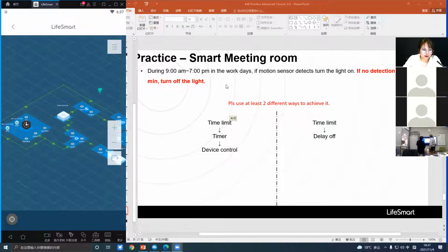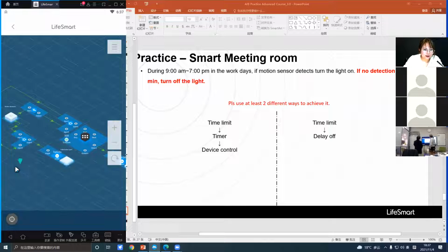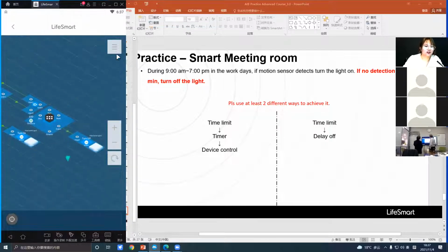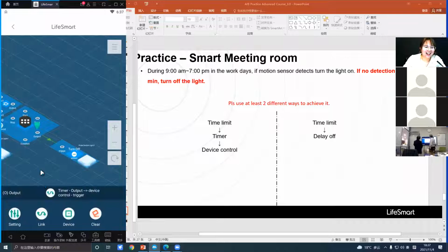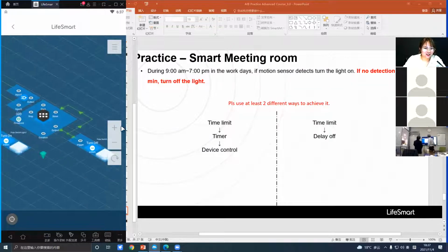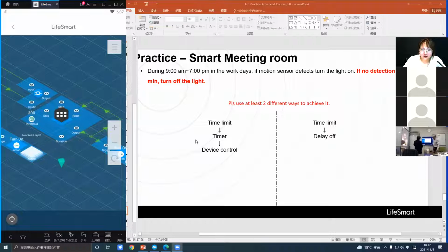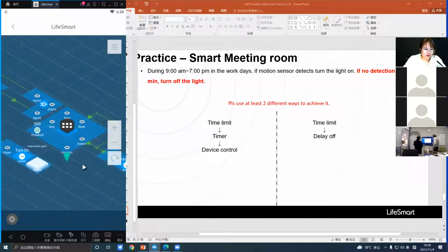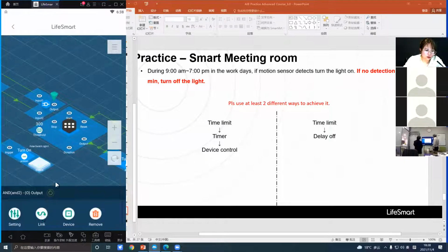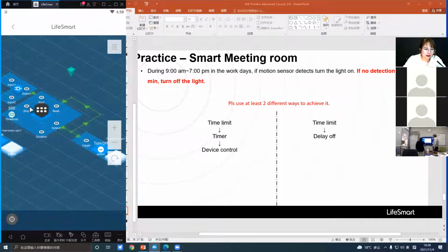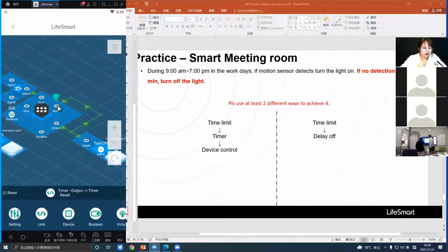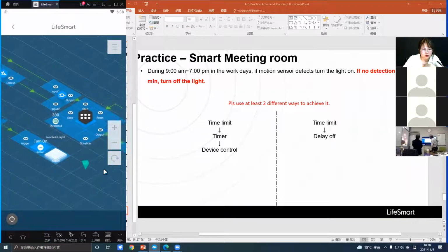In output, like to reset. Oh no, here you can see that. Oh yes, there is a reset. Oh, a new mistake. Thank you. Reset here. Thank you, Trung. Output to reset. Here output to start the countdown, and after countdown also need to set reset. You just remember that if there is a reset port, you must need to set reset. Here there is a reset, so you need to set it, or it will not work.